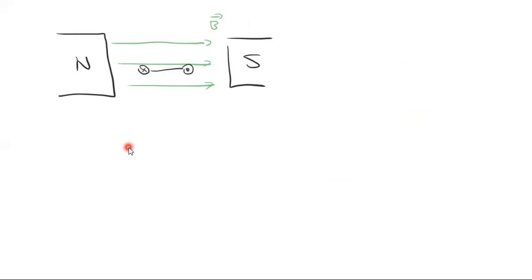If you use your right-hand palm rule, then you can see that if it's going in, it will experience a force downward. On the right-hand side, because the current is going outward, you experience a force upward. And because torque, which is what you need to get things turning, is equal to force times distance, and you can see that the center is here, so you've got this distance over here. That will create a torque.